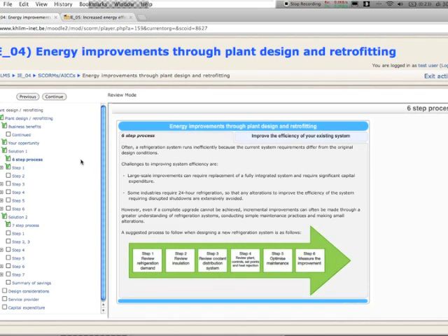Like I said before, the first step is to review your refrigerant amount. Know how much you have to cool, and why you have to cool. Then review your installation. That's a visual check. Then review the coolant distribution system. Then you go over to your plant controls, set points and heat rejection. Then it's important to optimize your maintenance.